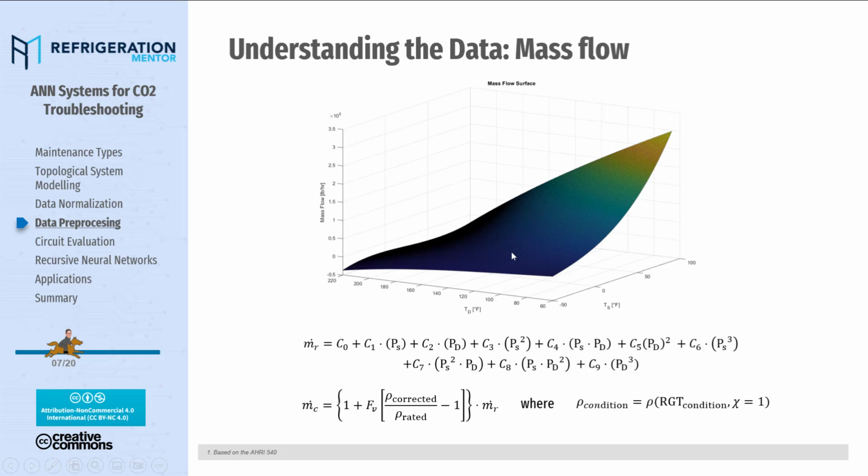About mass flow, it is the amount of refrigerant per unit of time. So commercial software calculates this value based on a polynomial regression in a calorimeter, but this data can be used and corrected by us to determine an average or estimated value in our system.